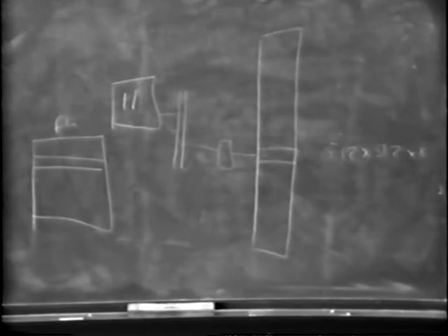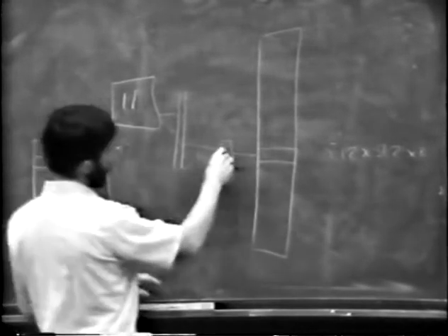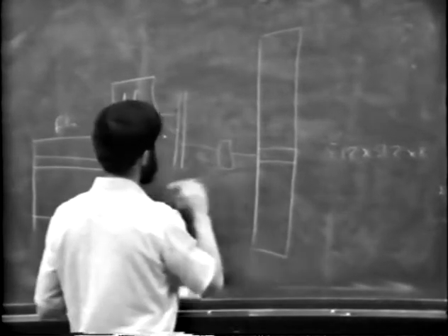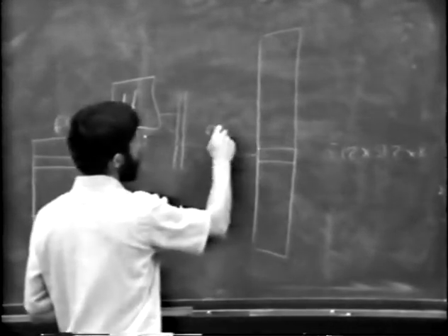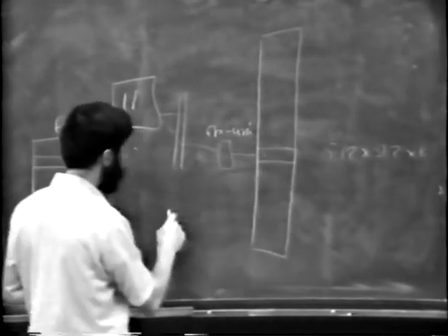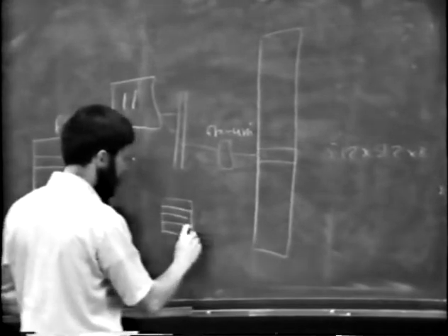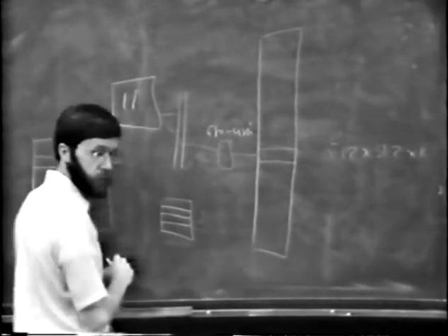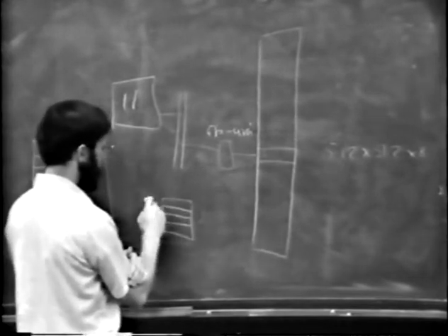However, if they were to build this frame buffer for us, we wanted a new kind of interface. Instead of having this interface, we wanted, scratch theirs, a frame buffer to unibus interface. And what this looked like on the unibus was 4 registers. The first register, let's call it status.